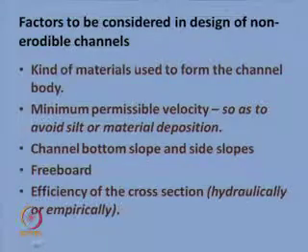What are the factors to be considered in designing non-erodible channels? Of course, when you design the channels, especially the non-erodible channels, you have to consider some of the factors. The first one, as it is being suggested here, is the kind of materials. So, what is the material you are going to use to construct the channel? That is quite essential, because it is the material that determines the roughness